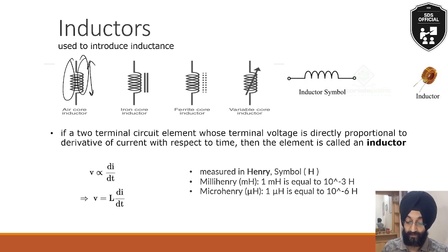So you can simply over here assume that inductors don't allow any change in their source, either it is voltage source or current source. If there is any change in the current supplied to the inductors, they always oppose the change due to the production of induced EMF. You have to remember this. So inductors do not allow AC to pass through them because they are offering the changes in the currents, and the changes are not accepted in the inductors.